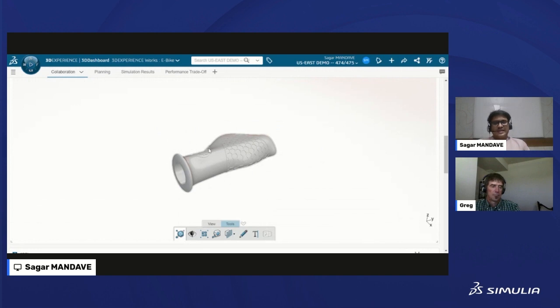But right now the handlebar grip is a single geometry, so I'm not going to demonstrate it, but it is there. Also, this is an explode. Likewise, if you have an assembly and you want an exploded view of it, you can just click on that. The assembly will explode. You can have details, or you can see each and every part.